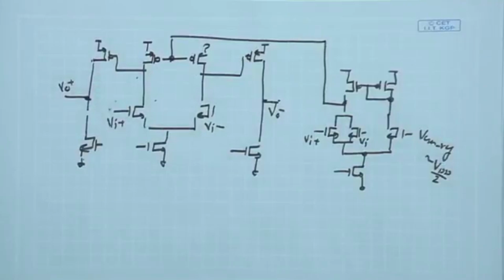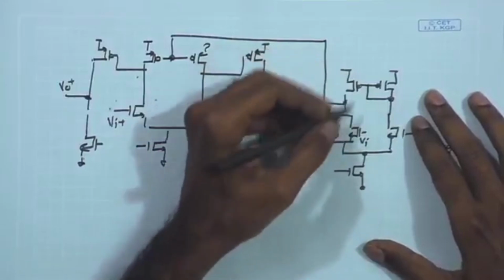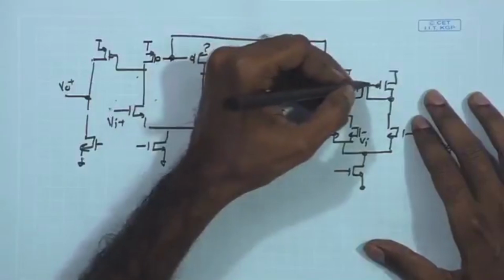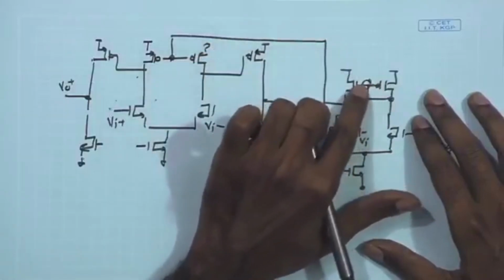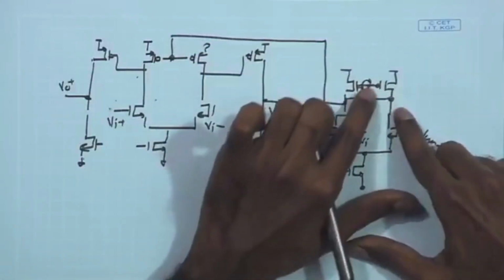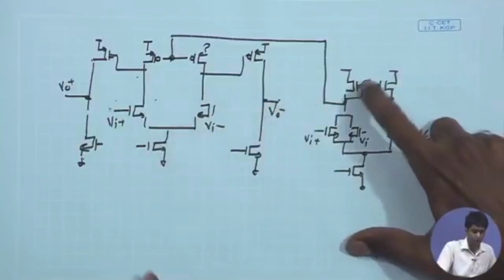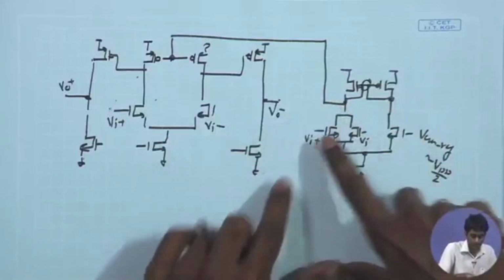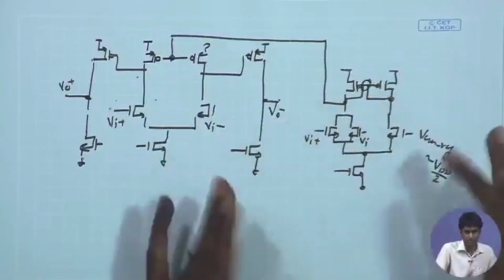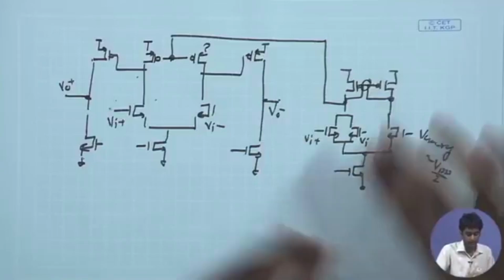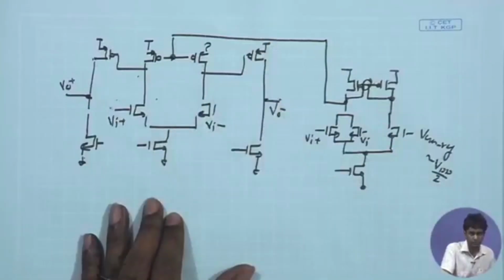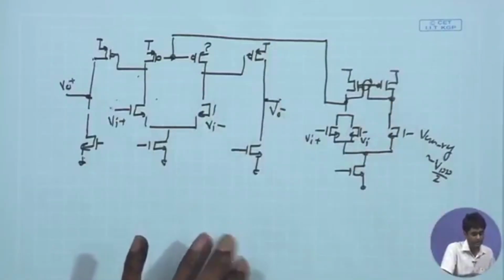So, this is what we discussed, and we also suggested that we get rid of the current mirror load and have a diode connected load, disconnecting this node. For the diode connected load you have to disconnect this, otherwise you are shorting both the outputs. So, you have to disconnect this central connection and make both of them diode connected, so that the gain of this stage is given by GM1 upon GM2, and as a result you have the overall gain of the common mode feedback loop given by GMRO of the two stages. This is going to give you unity, and there also we discussed that